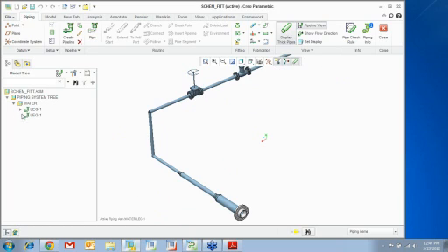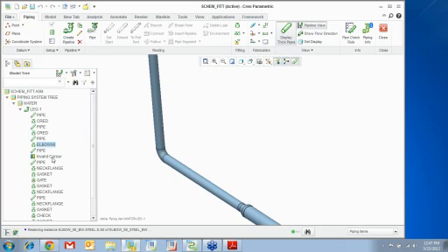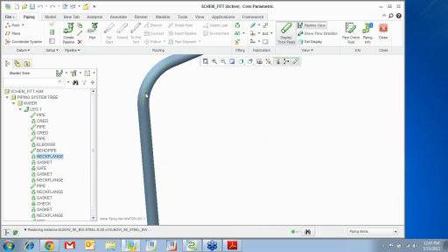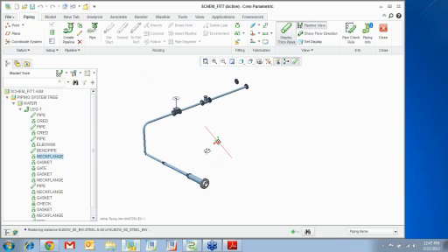And now also notice you have two invalid corners. So when you right click, you can choose an elbow or a bend. So if I go elbow here, you see there's an elbow. I can go bend and you see I get a bend. Right? So this would be like schematic driven piping.